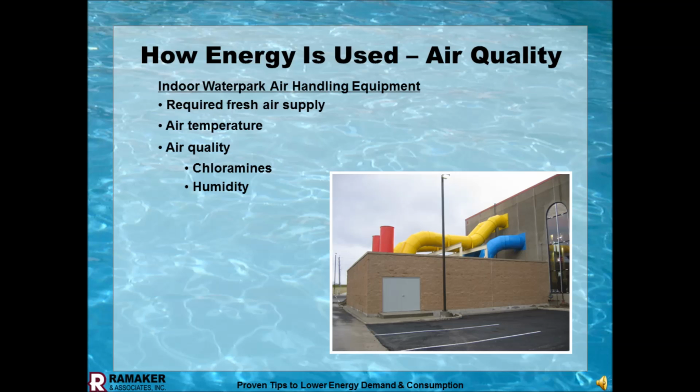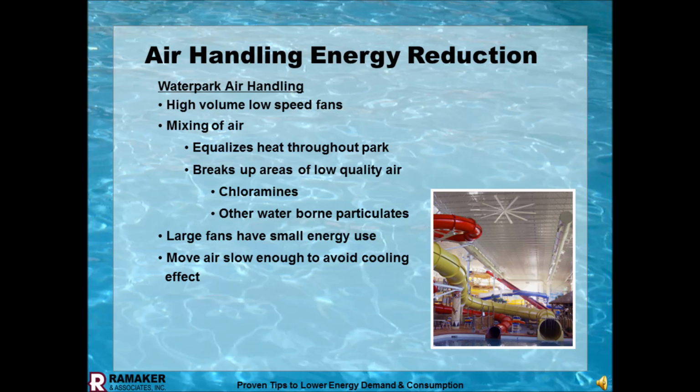Then it evolved into heat exchangers, so that the air being exhausted was passing through the heat exchanger, capturing the heat to put in the incoming air, but it's still 100% fresh air. The project was completed about 1 year ago. We put VFDs on the fans, and we put occupancy sensors. What we did is monitor people walking in, people walking out, what your water park capacity is, and ramp the fans up and down based on that.